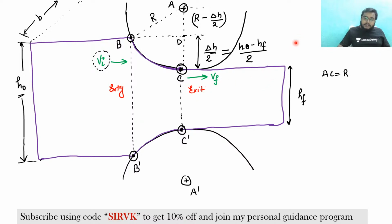What is the width? I have assumed the width to be constant, because basically the rolling operation is done to reduce the thickness. H naught was earlier there, now hf is there, so the width would be the same.